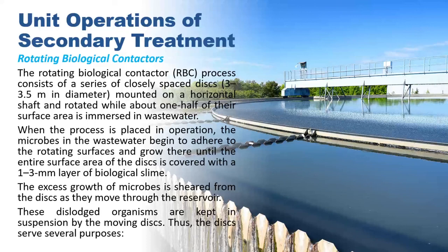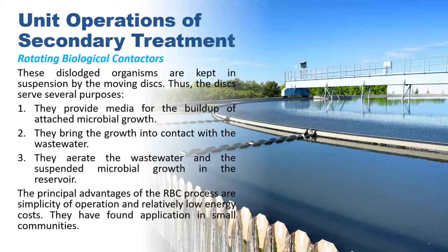Thus, the discs serve several purposes. They provide media for the build-up of attached microbial growth. They bring the growth into contact with the wastewater, and they aerate the wastewater and the suspended microbial growth in the reservoir. The principal advantages of the RBC, or the rotating biological contactor process, are simplicity of operation and relatively low energy cost. They have found application in small communities.